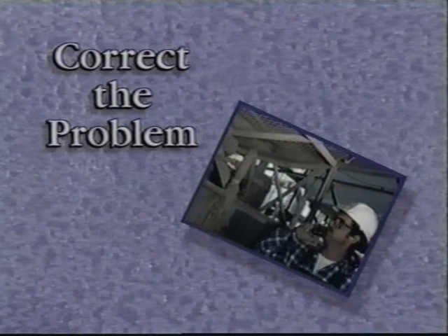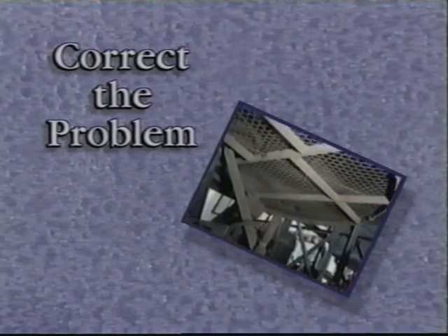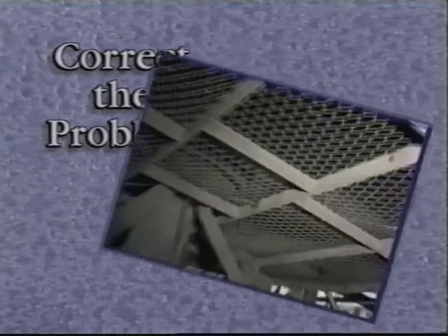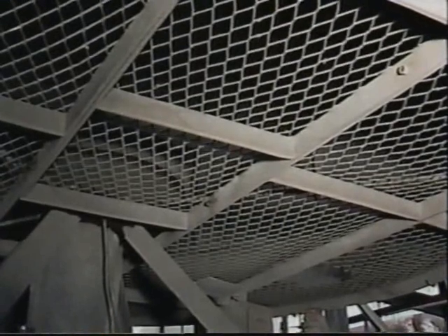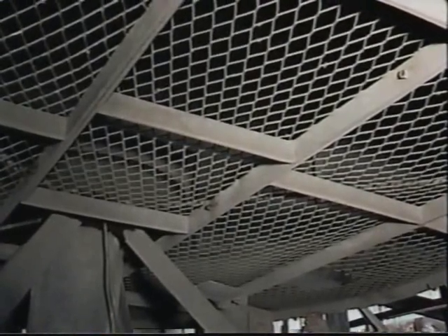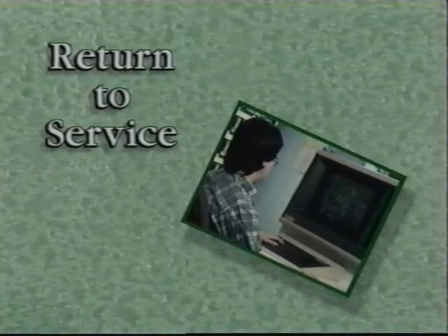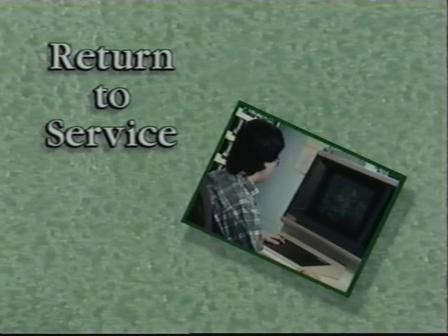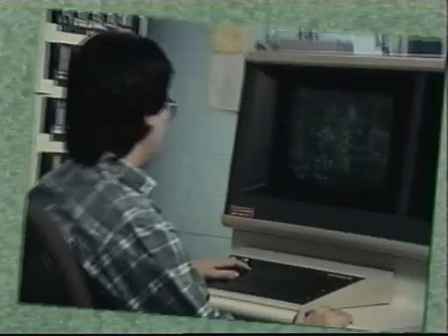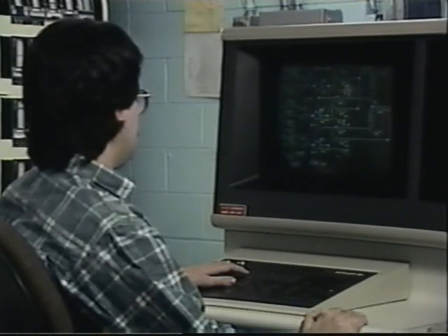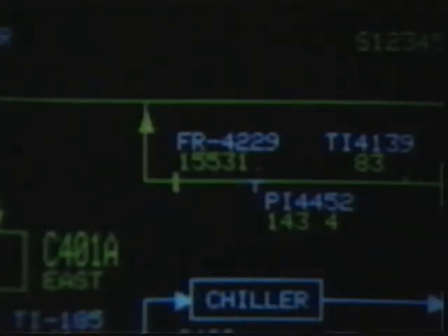The operator has the motor restarted. If it gets hot and shuts off again, he may have to get the motor repaired and cut back on the feed rate to the unit. When the fan motor is running properly, the operators will still need to make sure that the problem is fixed and that the hydrogen make flow rate has returned to normal. And if there was an adjustment to the feed rate during the troubleshooting process, it can be returned to normal.